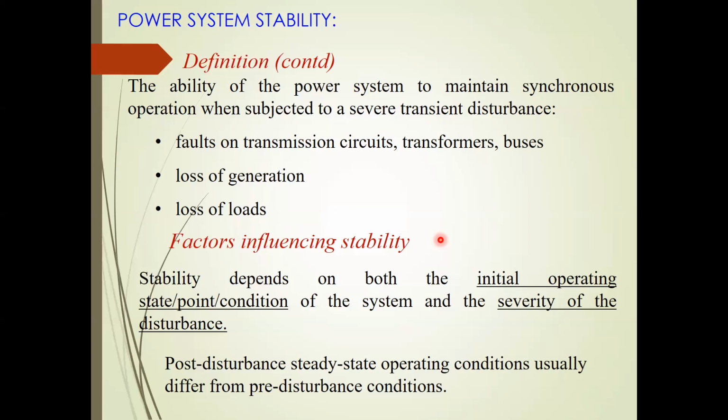Now, in that case, if you experience a 20% increase in the load, what will be the impact on the generator? It will slow down. Yeah, because do you think the generator output power can be increased by 20% above the rated value, I mean, right? Above the full load condition, it will not be possible. You can overload the generator. That is possible by 5%, 10%. In some cases, it is possible.